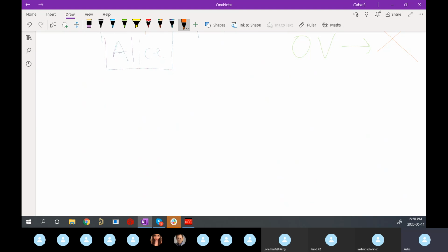So let's approximate each of our microcontrollers as just a switch for now. This is Tim. Let's put Alice here for the time being. So she also has the capability to pull this down to ground if she sees a fault. And then let's say this goes to our alarm. So let's say we have a pull-up resistor.